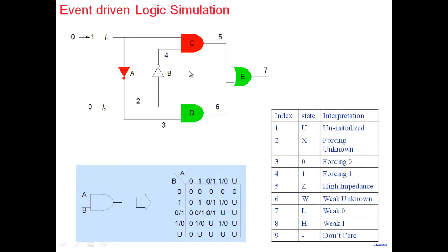And we also saw that logic simulation is being done in order to verify the correctness of the logic. That's one aim. And in order to do that, one may want to do a multi-valued logic simulation. This shows a 5-valued logic simulation. As I was telling you, in VHDL you have all these different logic possibilities. So the simulation of a gate is not in terms of simply binary inputs, but the inputs could be more complex, and some of these are given here.